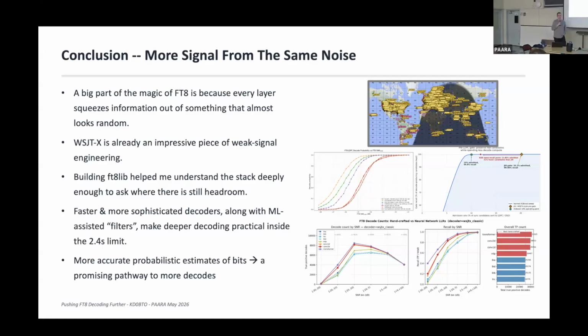I think it will be that 40% in the weakest signal regime, because that subtraction really does play a role. And maybe we're just using this fancy neural network to get stuff that WSJTX would have gotten if you had done signal subtraction. That is the big open question, but the way to go is to make this thing as good as possible and then thread it through the whole thing, doing the whole subtraction. And then you get those weak decodes that you never saw before. You could then put those back into your training set, which is kind of what you were saying. It's a flywheel, which is the term people like to use for the process.